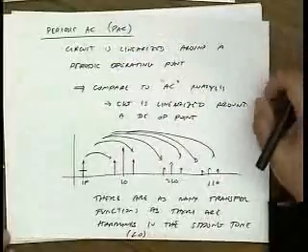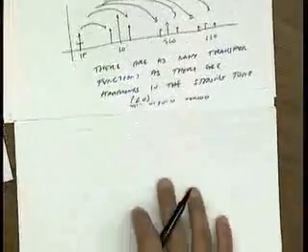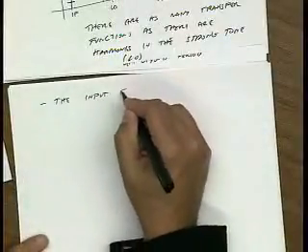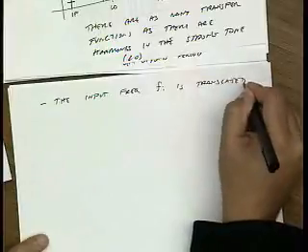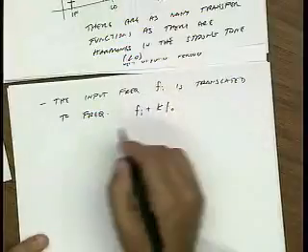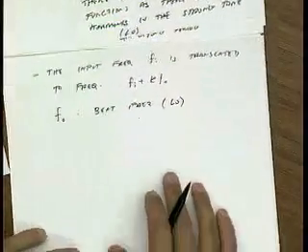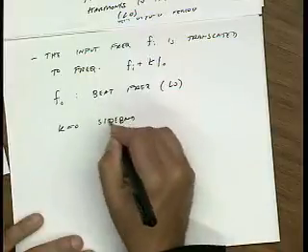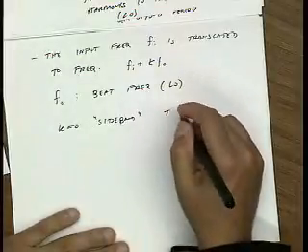Okay, so what we need to do is specify a reference. Basically, we have to specify which transfer function we care about. So the input frequency, let's call that Fi, is translated to frequencies F input plus K F naught, where F naught is the beat frequency, which in a mixer is just the LO frequency. So for instance, the K equal to 0 sideband. That should be the same as the DC component of the LO. So this is the time invariant behavior.